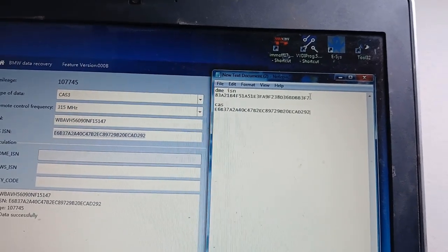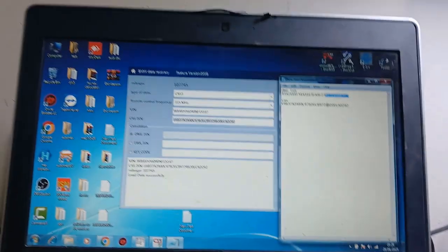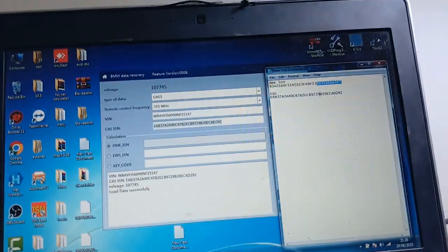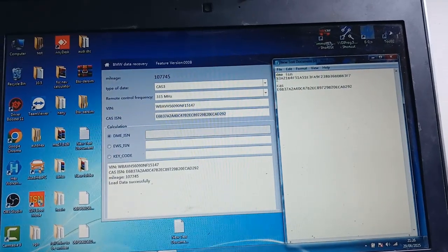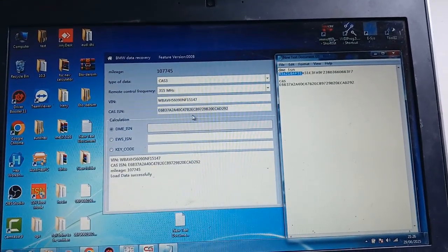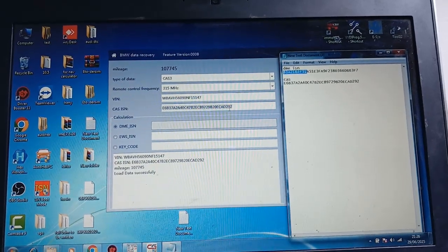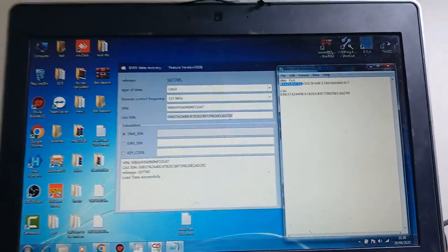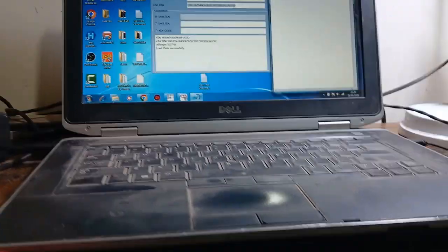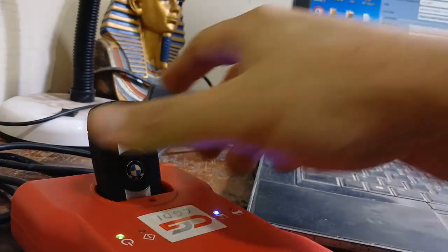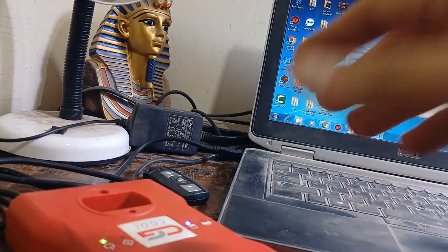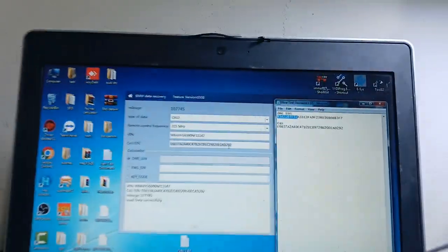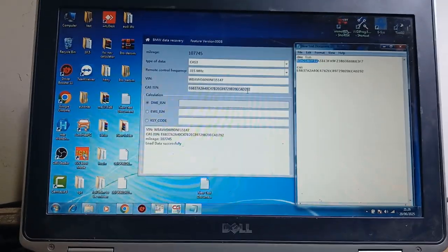If you want to program a key, you must enter this one. Here also I have the DME ISN, I can double check that, but this one should be okay if you program a key with this Eeprom and Flash file for this encrypted version of CAS. So if it is easy to fix the CAS and make another key, maybe I can write the whole file on the second problem, or if I have the same problem, and make a key, and it will be too fast. Okay.